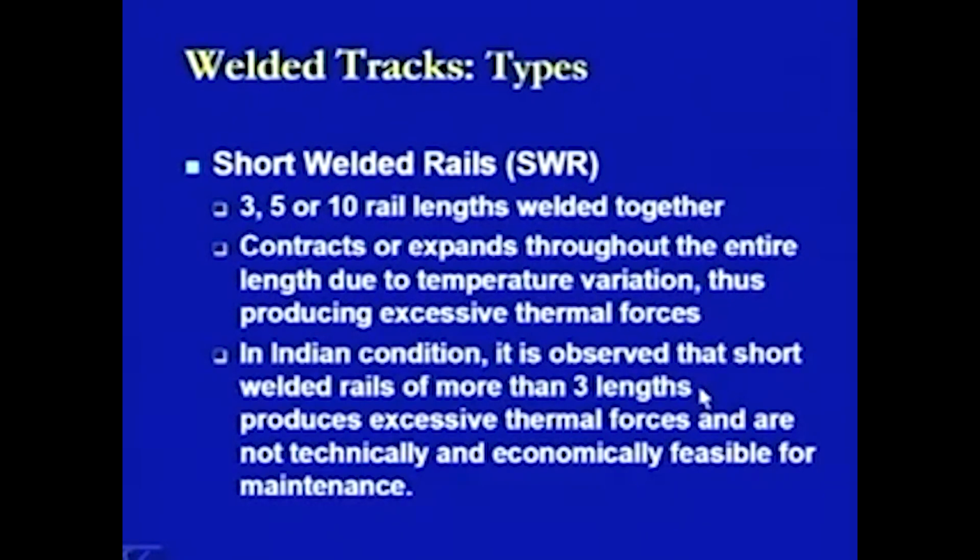And in Indian conditions, as we have seen, there are variations of temperature going from very low to very high conditions. So, in that sense, it is observed that short welded rails of more than 3 lengths are going to produce much higher thermal stresses.